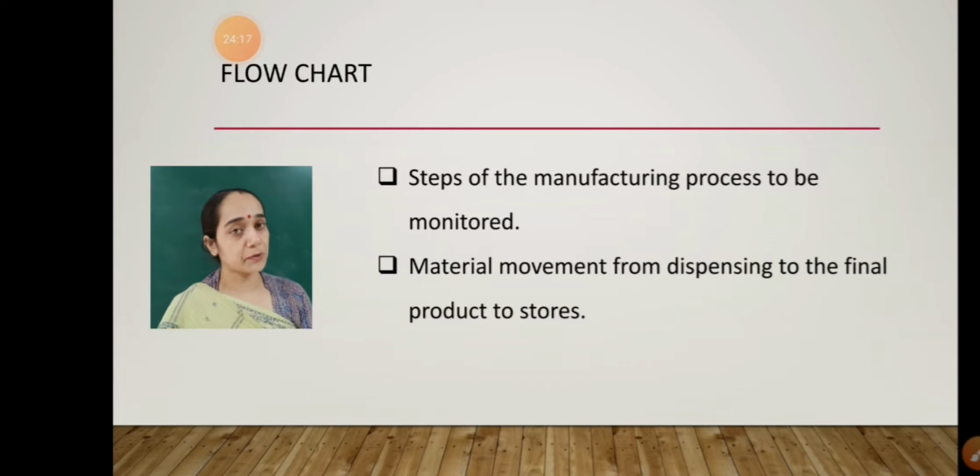It will be active pharmaceutical ingredient, diluents, disintegrant, glidant, antiadherent. All the things will be weighed in a specified amount and quantity, and then they will be uniformly mixed by using a suitable mixer for a particular duration. After mixing, I am checking the flow property, meaning whether my product has a uniform flow.